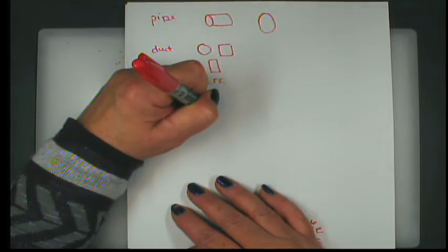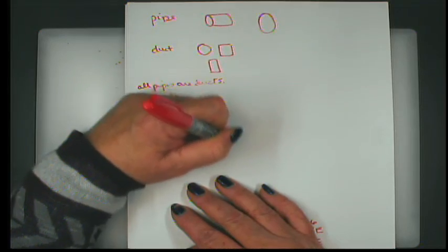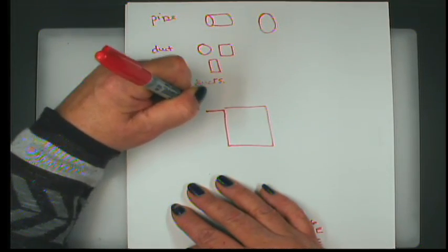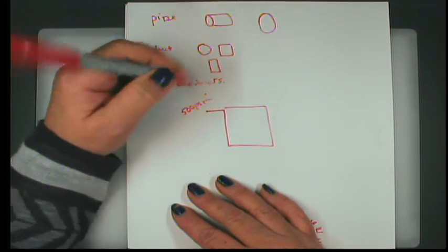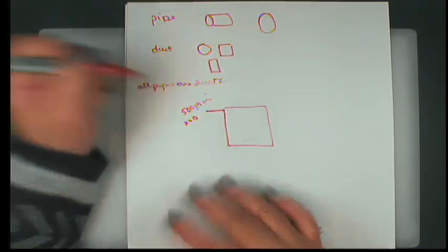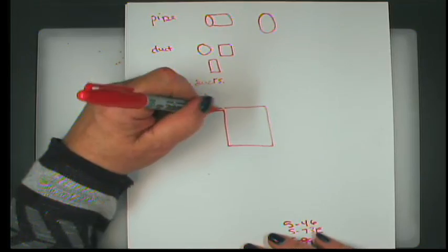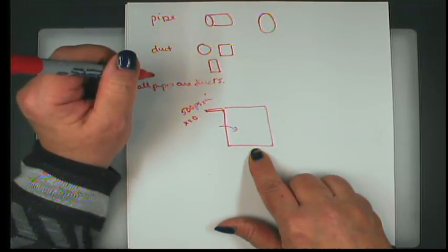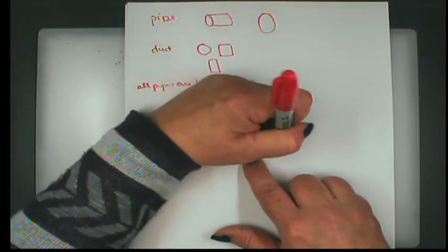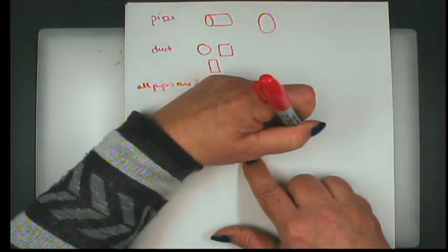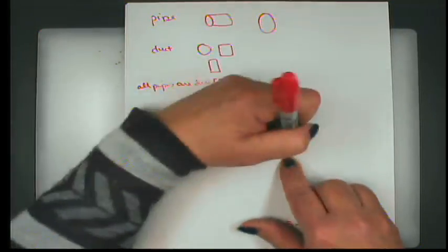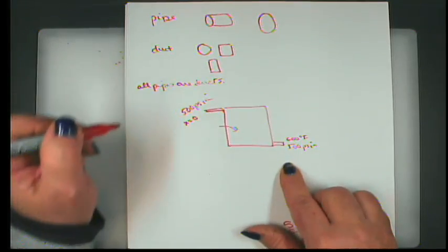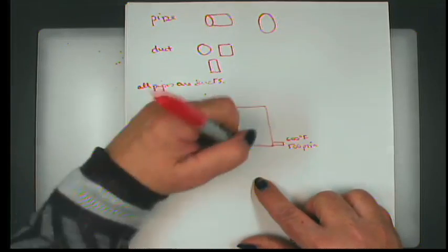589 says we have water that enters a boiler at 500 psia as a saturated liquid. Okay. That means X equals 0. It goes into the boiler, and it leaves at 600 degrees Fahrenheit at the same pressure. Calculate the heat transfer per unit mass.